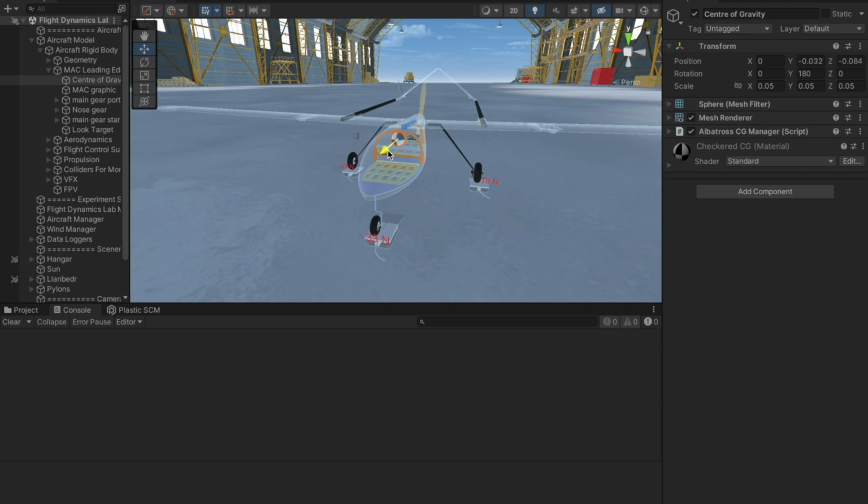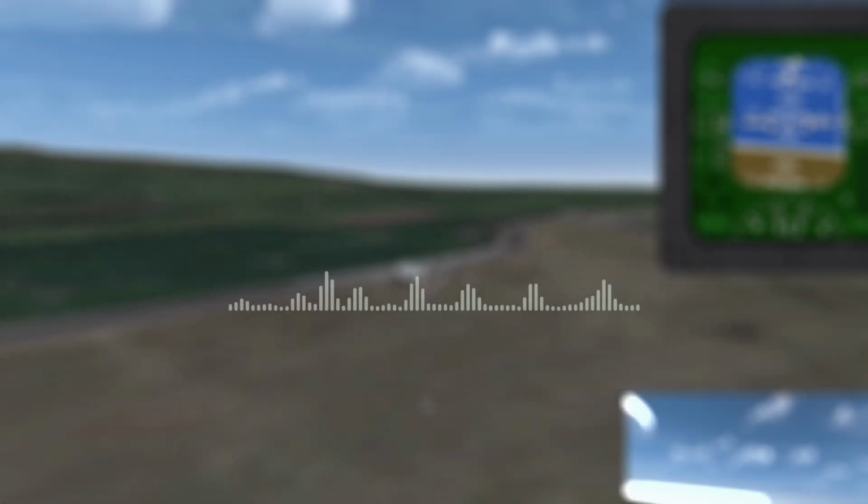The analysis of the weight reaction forces and the resulting moment was performed to first estimate a reasonable range of CG positions for the aircraft. For a tricycle aircraft, you normally want 10% of the total mass concentrated through the nose gear when calculating the relative loads around the CG. As a result, the front of the aircraft is given enough mass to provide enough controllability during nose gear steering without making the front of the aircraft overly heavy.